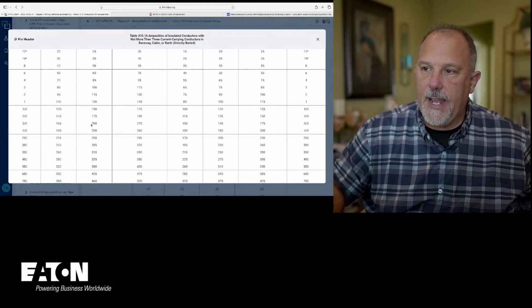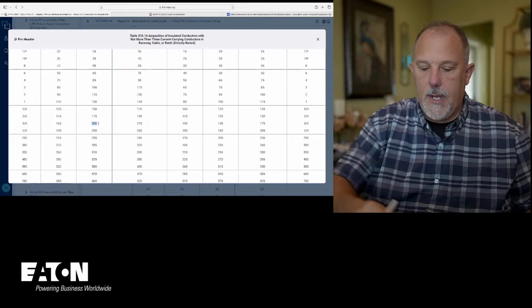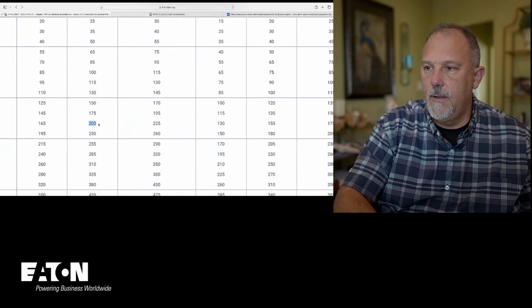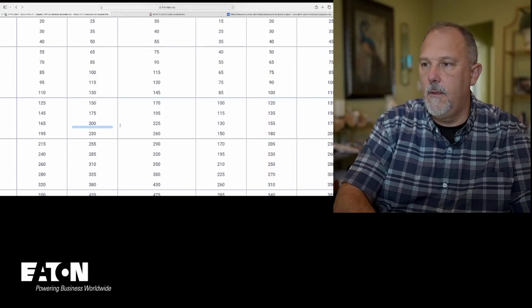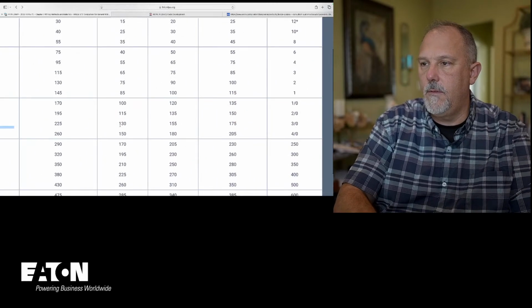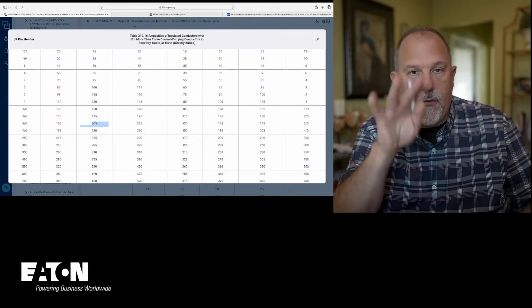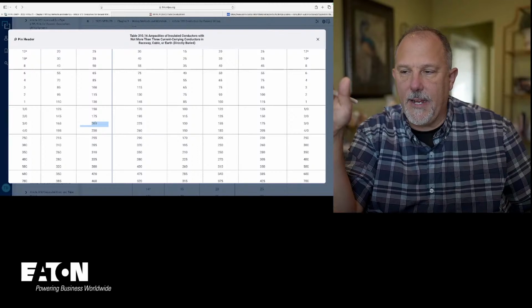I could say I'm going to go with a 3/0 conductor, and I'm going to go with 4 of those. That gives me my 800.